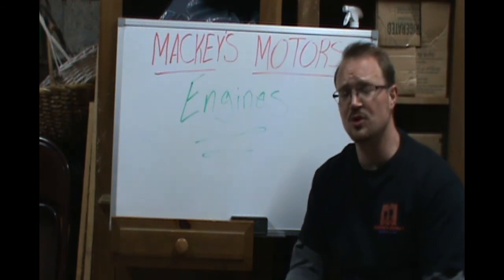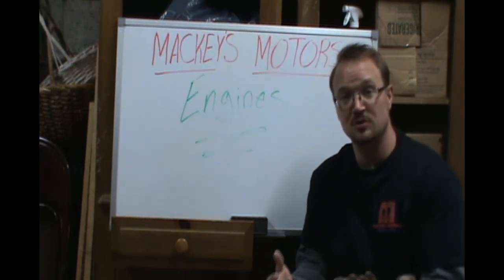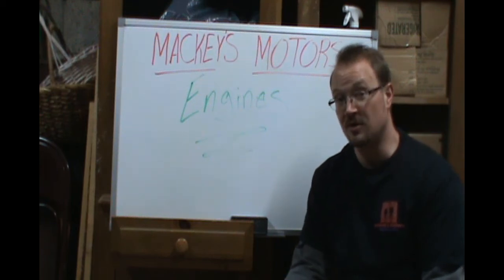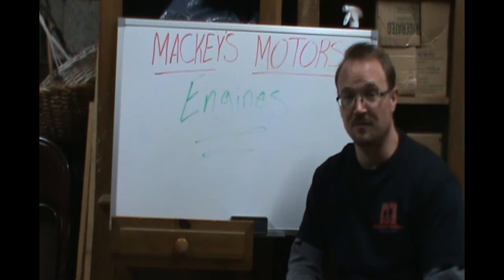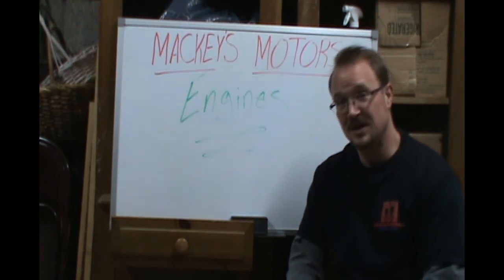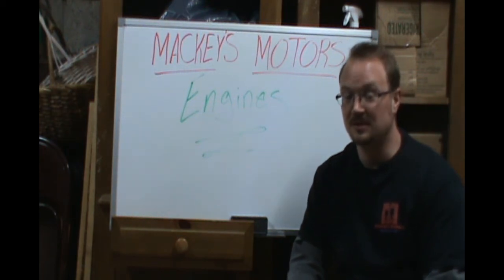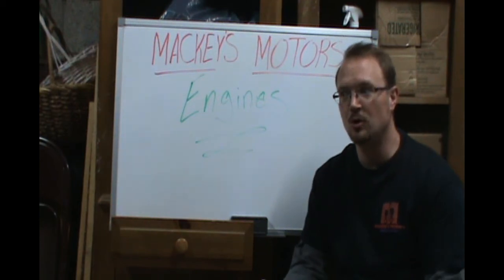So making sure you know your tune-up intervals, making sure you know what components need to be replaced under a tune-up, checking an owner's manual, checking with the manufacturer, doing some online research. You can better educate yourself in knowing what needs to be done and at what interval. Same goes for any of your vehicles. If you drive hard, if you beat it, if you drive it like you stole it, chances are you need to be on top of your maintenance a little bit more often than what the manufacturer recommends. A simple check of pulling one spark plug, checking wires, checking belts and hoses can go a long, long way to prolonging the life of your vehicle and getting that better mileage.